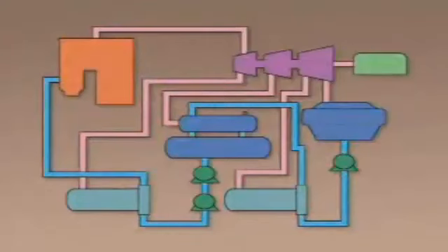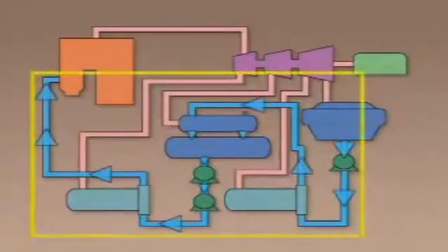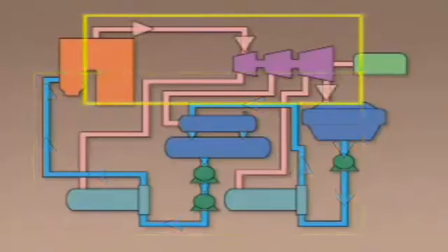For instance, it allows the purified water in the steam-water cycle to remain within a closed loop so that it can be reused. Specifically, the condensate is pumped from the condenser through the condensate and feedwater system and returned to the boiler, where it is heated to produce steam. The same steam that eventually reaches the condenser again, where it's condensed back to water so that the cycle can continue.